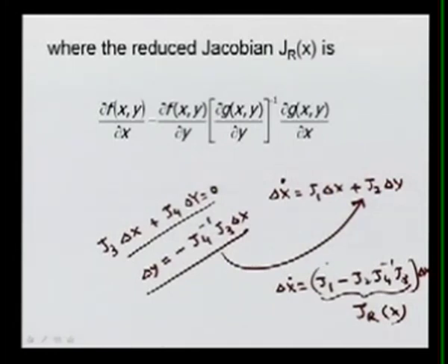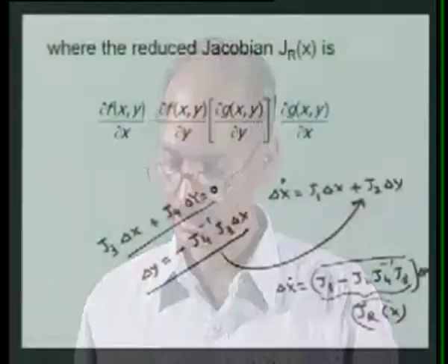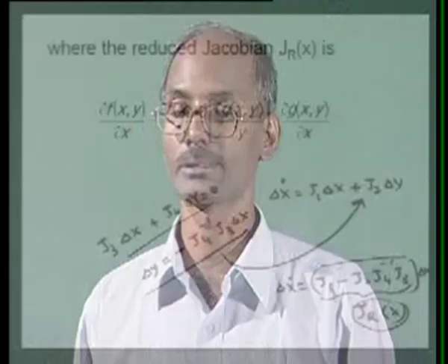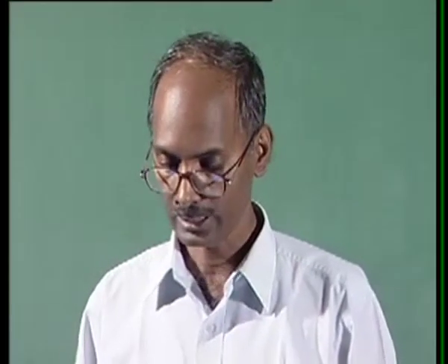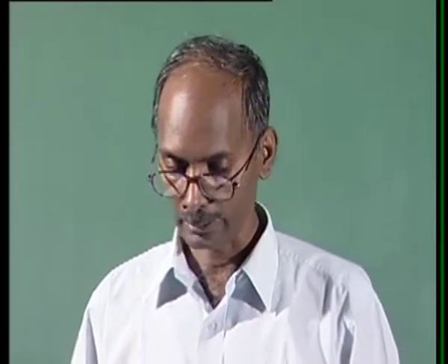Now this matrix gives the information, just like the steady state power flow Jacobian. We can analyze this matrix to get information about the condition number and other things, and about the system stability conditions. We can go for the eigenvalues of this matrix, and based on that we can conclude several things.